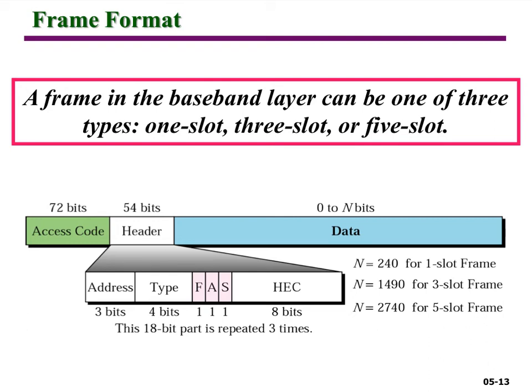You're not expecting that we hop during the frame transmission. The frame is transmitted as one unit on one frequency. So with a 3-slot frame, you have 3 slots with the same frequency, which means that the hopping frequency is dropped. Or if you have a 5-slot frame, then you hop every 5 slots, not every slot.